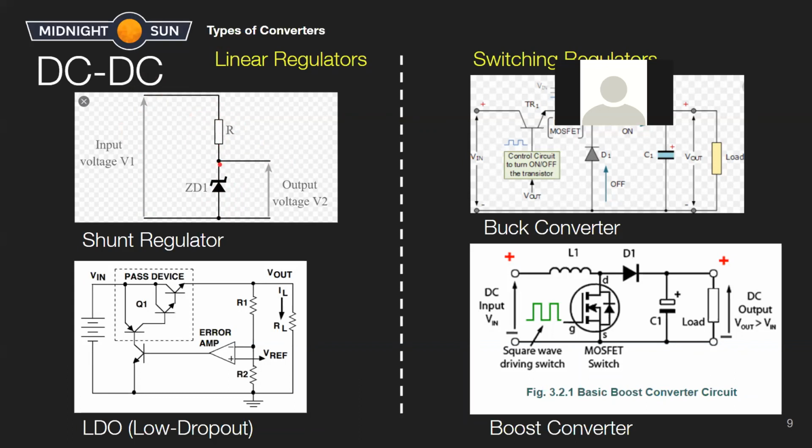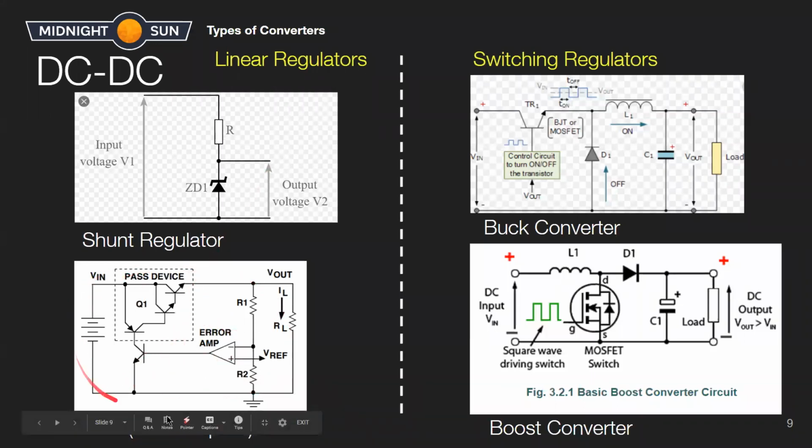So there's a small amount of current that goes through this diode, and the rest is powering your circuit that's using this input power. This is really how it works. It is a linear regulator because it is dropping voltage across a passive element, and that is the way that you get a reference. And the way that LDOs work is based on this logic, so I'll try to walk through that again.